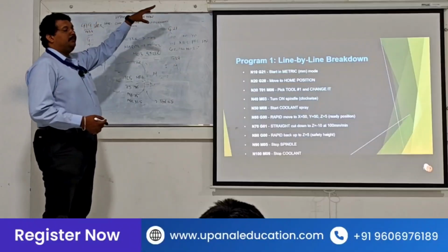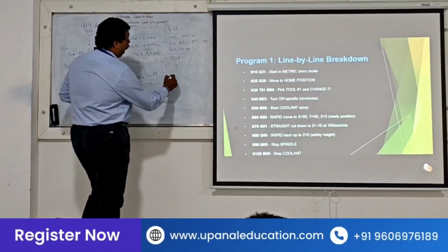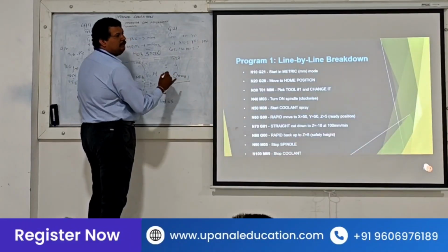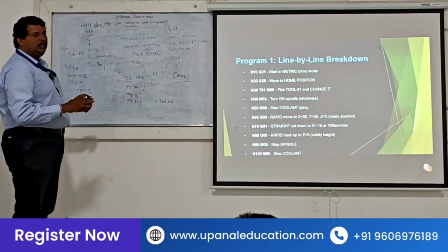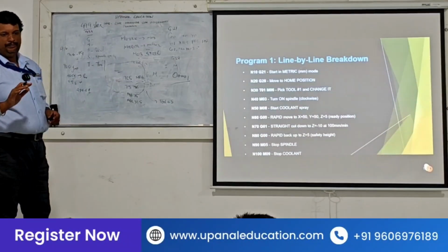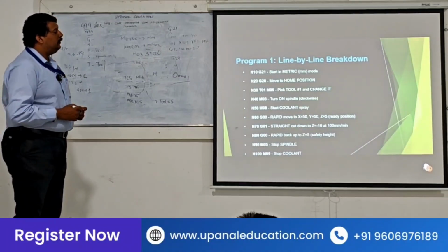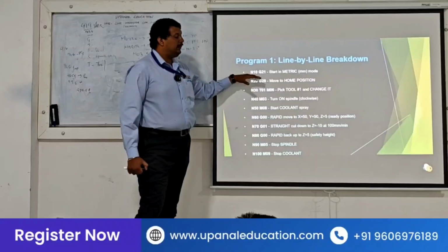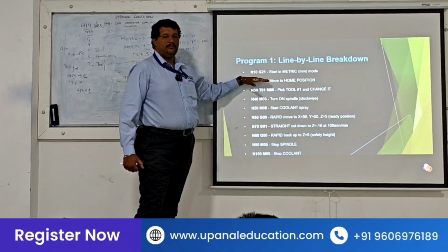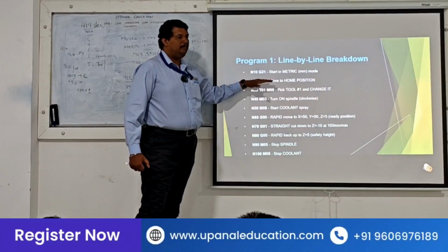Then, the first line in the CNC program will be something like O0001. It's the number of the program. We are giving a number for the program. It will always start with O. That's the only place where we use the O. Then the next line will be N10 G21. What is G21? We are telling the machine that you have to work in mm.